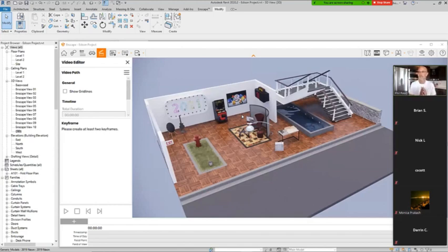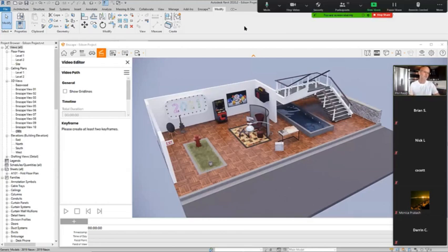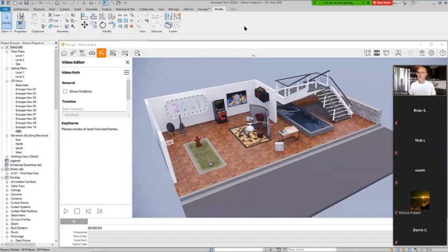And here's the overall scenario. I would argue that you don't want to create individual animation paths, export them individually, and then have to go through the process of loading them and rendering them individually. So let's say you've got a dozen animation paths and they're each going to be about 10 seconds long. It will take no time to render that as an entire sequence, but if you have to keep opening, rendering, closing, importing, rendering, closing, it's that time between your animations that often takes time. So we're going to create a scenario where we're going to create a continuous cut animation. It's going to go from one sequence, it's going to jump to the next sequence, and we're going to be able to animate multiple sequences all at the same time.